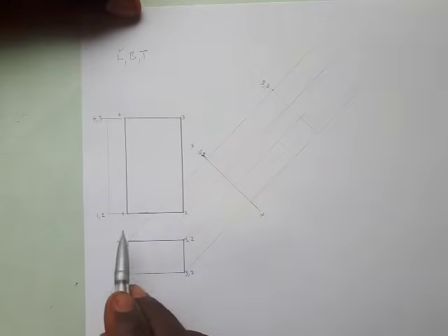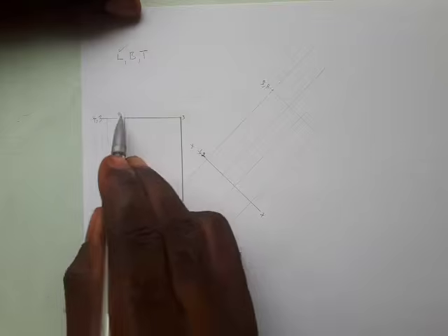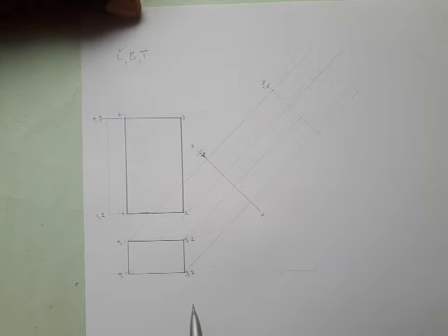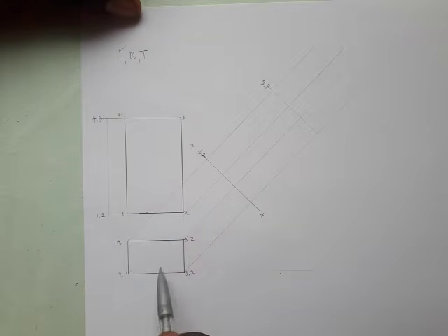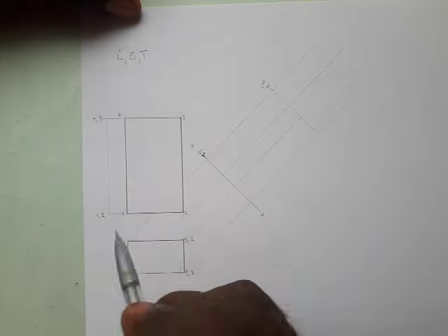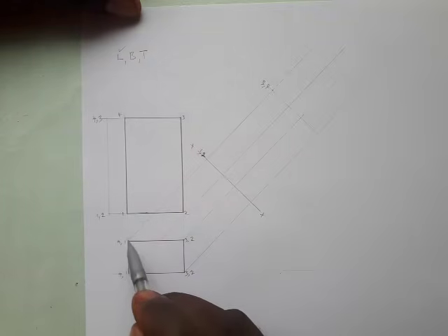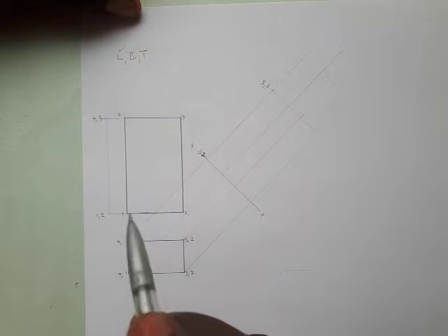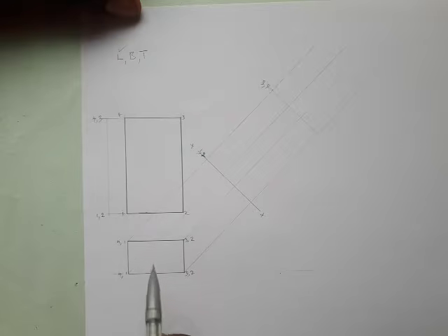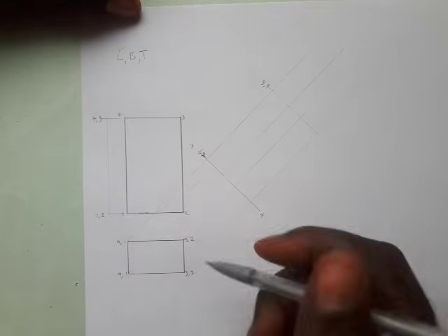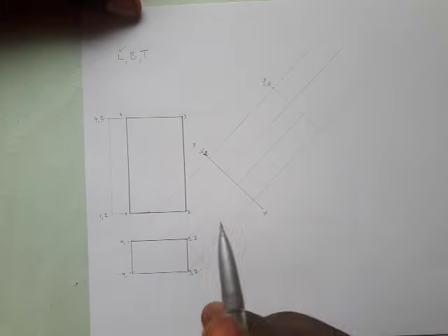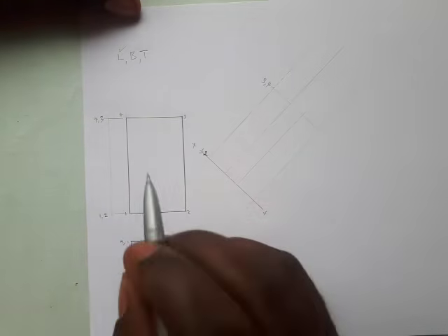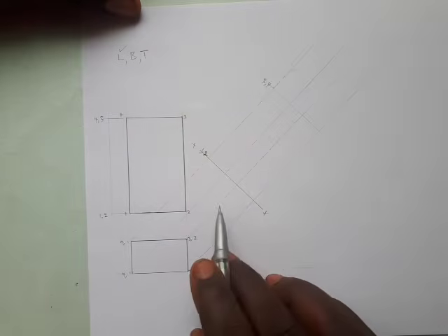Then this is what we're referring to as breadth. Any line that is moving in this form is breadth. We're going to settle everything. Then the thickness: you can see breadth both on the plan and in the elevation. You can only see length in the elevation, not on the plan, because the length is coming up this way, so you can't see it from the plan. The thickness you can only see on the plan. You can't see it here because the thickness is coming out of this paper. But it doesn't matter. Wherever you see length, breadth, or thickness, you can work with it.